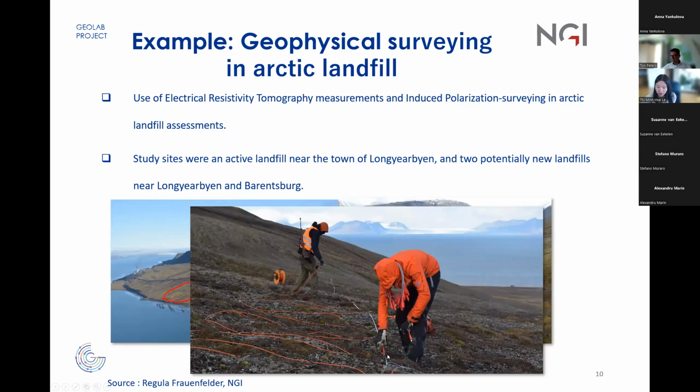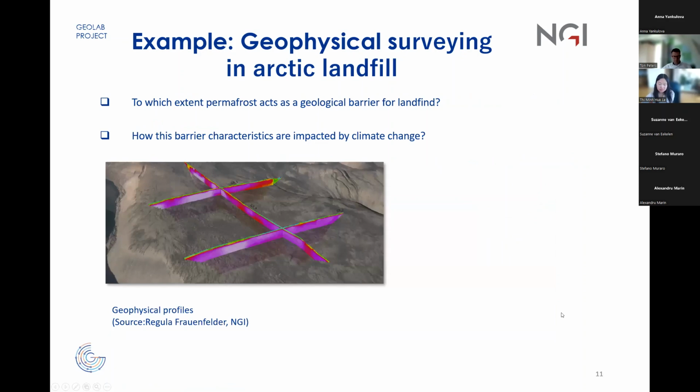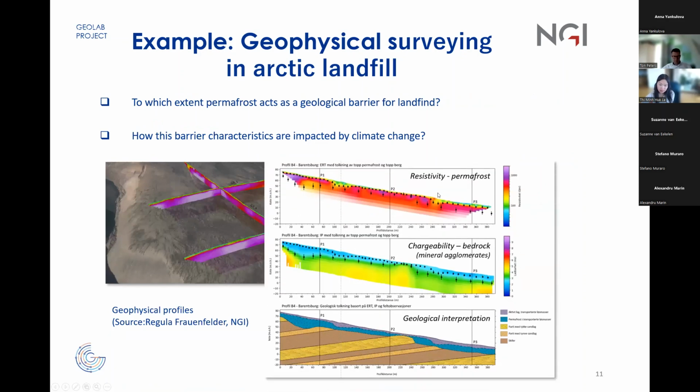The pictures just show how the study was carried out, much less complex than the pile study, because these are non-intrusive methods. Basically, they install electrodes in the ground and measure the conductivity between different electrodes. With the data, they can come back and process it with different methods to interpret the top of the permafrost and the top of the bedrock, and put it together with borehole data and field observations to construct geological interpretations, as shown in the pictures.